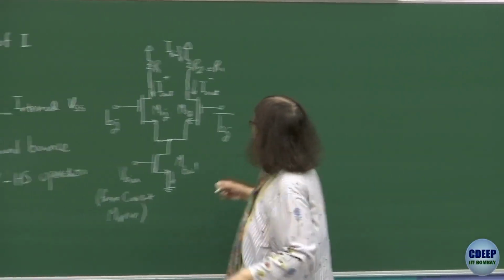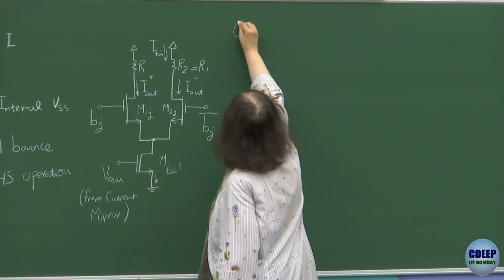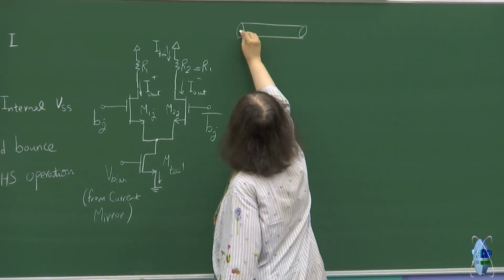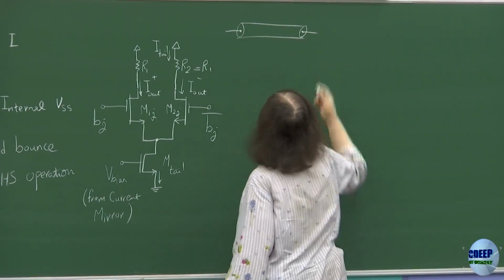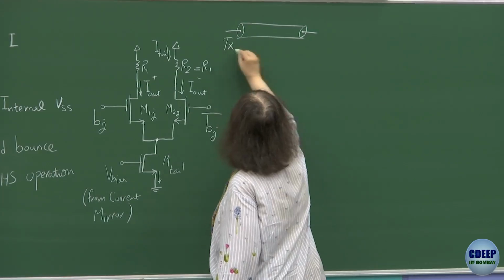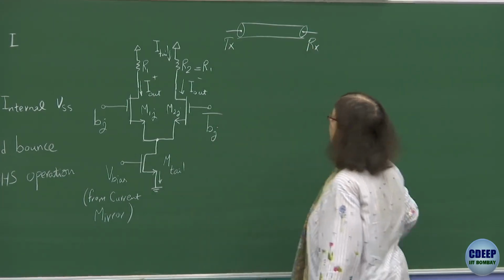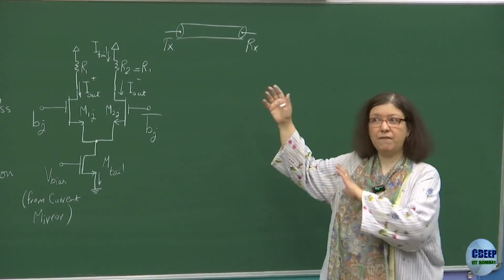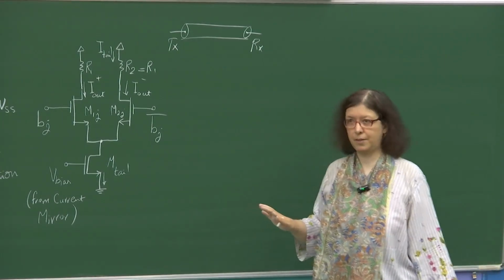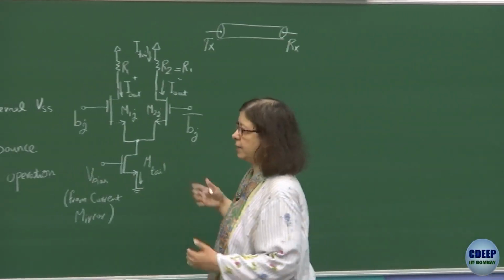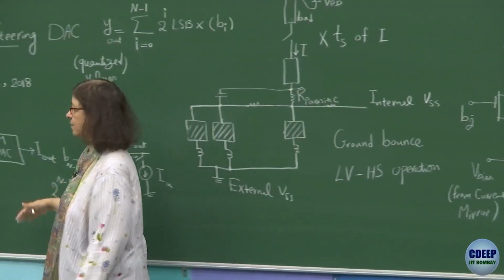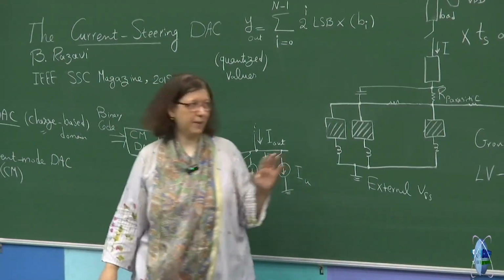So effectively, you need to drive a transmission line, say, or a cable. Say this is the transmitter and this is the receiver. CMOS will fail. So CMOS logic cannot be used for this application. That's why other logic families, where current mode logic, current mode signaling as it is also called, are practically used.